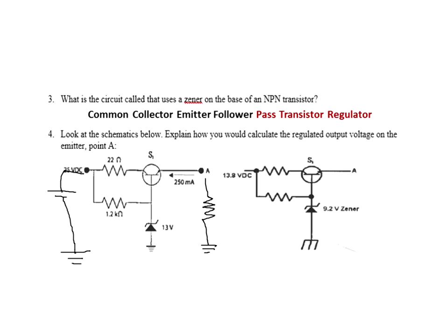That's a battery in case you didn't notice. So I'm putting 25 volts in over here. 25 volts in. And I'm going to regulate to some output over here. Why is it called a pass transistor? Well, all the current from the power supply passes through the collector and the emitter of the transistor. That's why it's called a pass transistor. All the current passes through the transistor. It's not really using the zener to deflect any current like in a basic zener regulator. Okay, so that's what it's called. That's why it's called that.